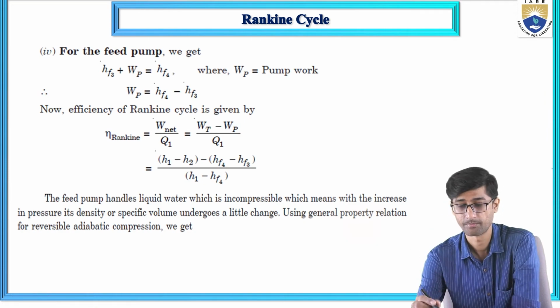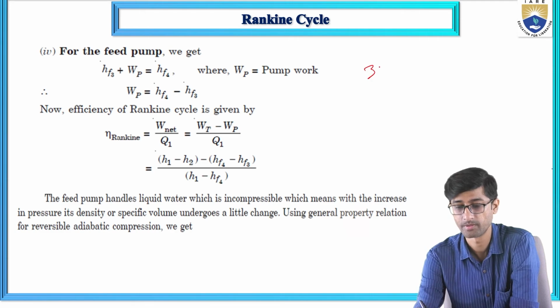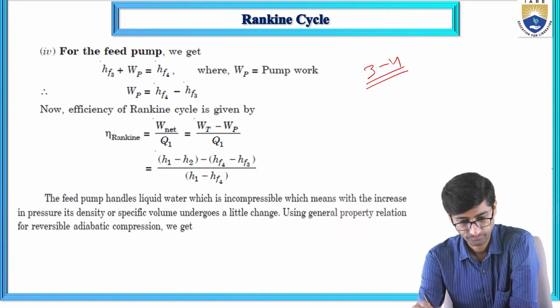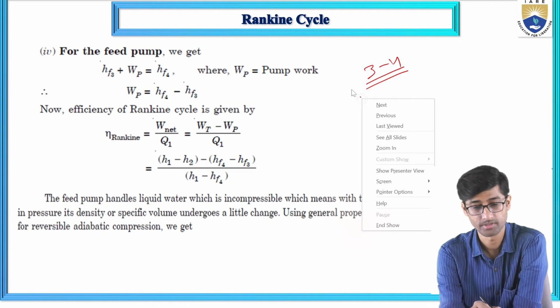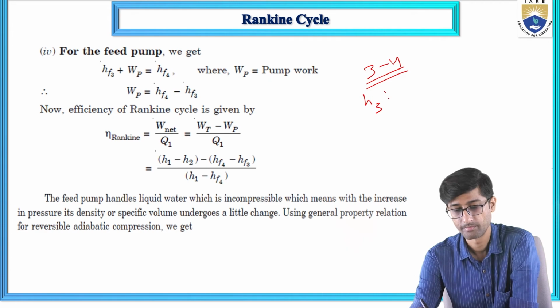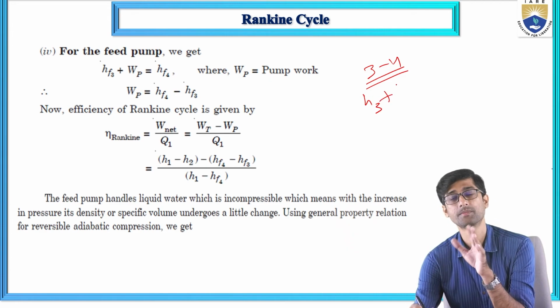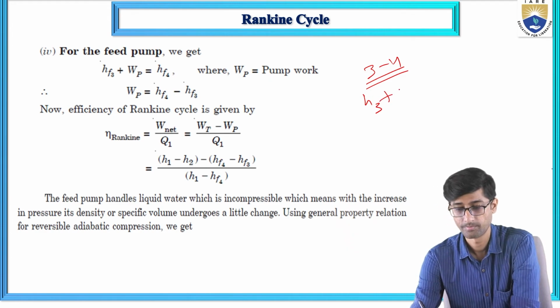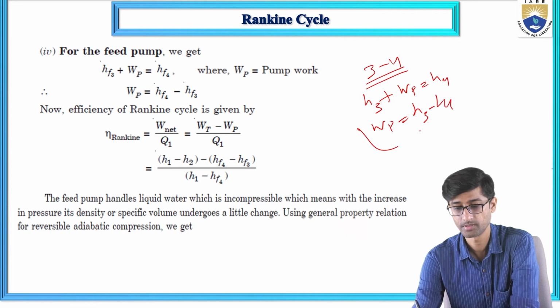The pump is the 3 to 4 process, the pumping process. Again, we are applying the steady flow energy equation to the pump. Neglecting kinetic energy, potential energy and heat transfer, H3 plus pump work is equal to H4. So what is the pump work? The pump work is H4 minus H3.